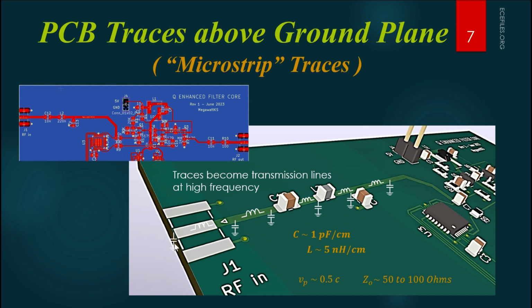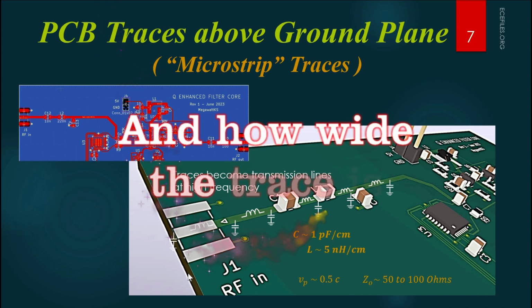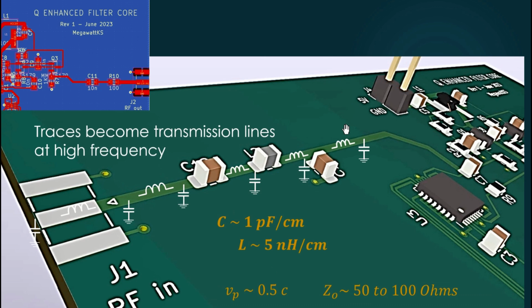And as we introduce an RF signal into this circuit, this capacitance and this capacitance, as well as all the loading here, draws current from the source, and that goes through this metal, and that's why I put an inductor here. So as the signal goes along, it encounters inductance all the way down. And I say that's very roughly about 5 nanohenries per centimeter. It varies depending on how thick the board is, how nearby the ground plane is. But these are very good ballpark estimates.